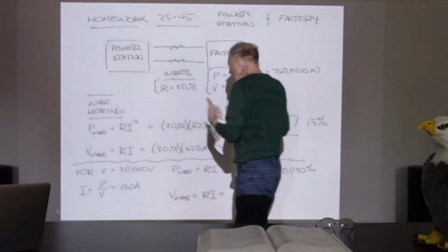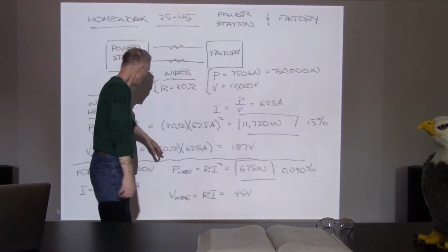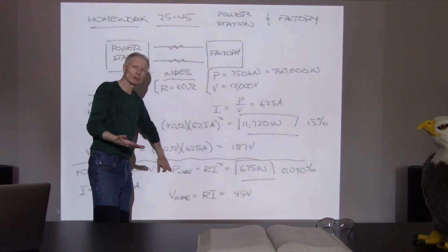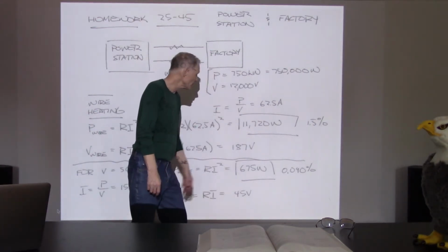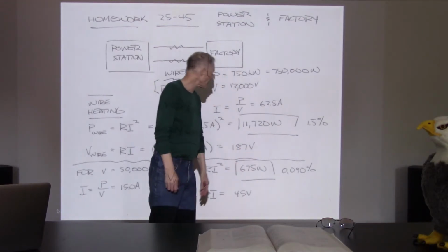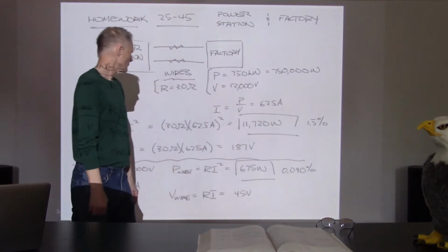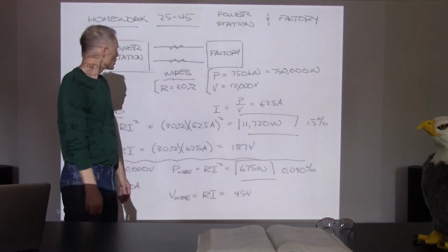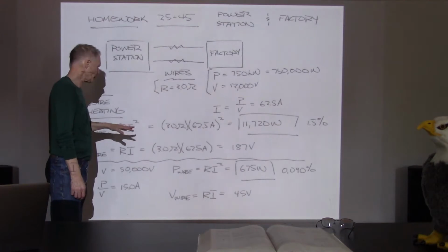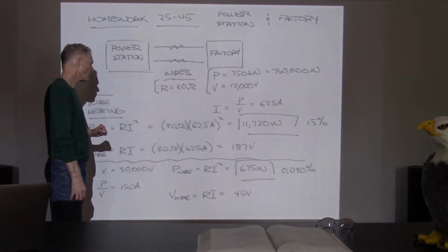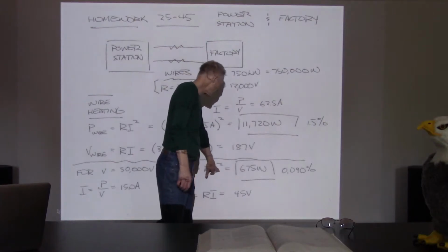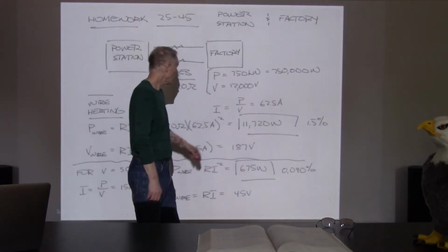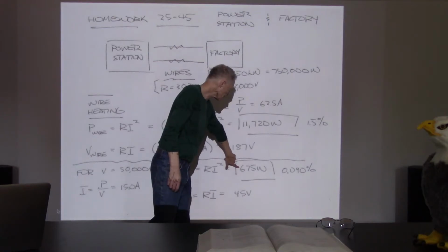Okay. Now when we do the wire calculations, we look to see how much thermal energy, what's the rate at which thermal energy is being generated in the wire. That's R times I squared. Ooh, it's down to 675 watts. That's a lot, right? So we reduced the current by a factor of a little more than 4. And so this is going to reduce down by a factor of 16 or more, and that's where it leaves us. So we're down to 675 watts,